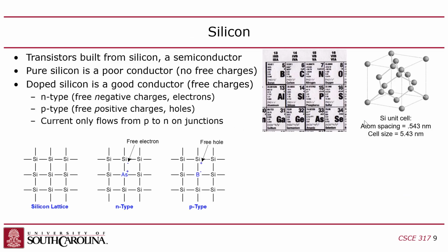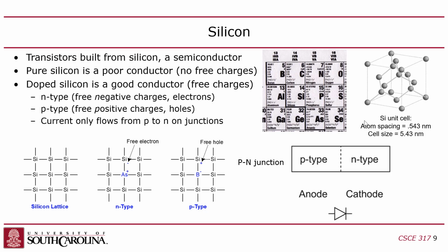Then we talked about semiconductors, and this is actually a new slide. I put a better slide in than the one I had last time. So silicon, as I mentioned, forms a crystal lattice, and you can dope it. You can add impurities. So this is the silicon lattice in 2 dimensions. This is what it looks like in 3 dimensions, which is, in reality, what it is. But in 2 dimensions, it looks like this. Every atom forms bonds with 4 neighbors.